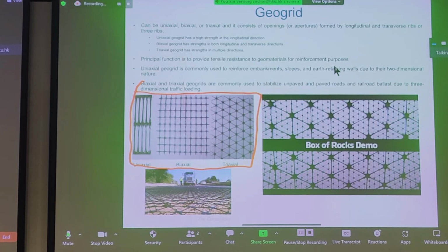You can see that these plastic sheets are very pervious. In fact, they use this for some sort of highway application here. They're so pervious that you're probably not going to use this for separation or membrane, right? And the plastic is actually quite strong in terms of tensile resistance, right? So we can use this to our advantage.